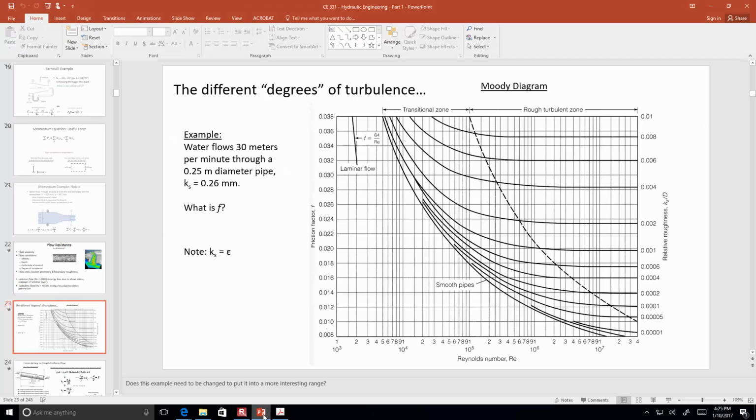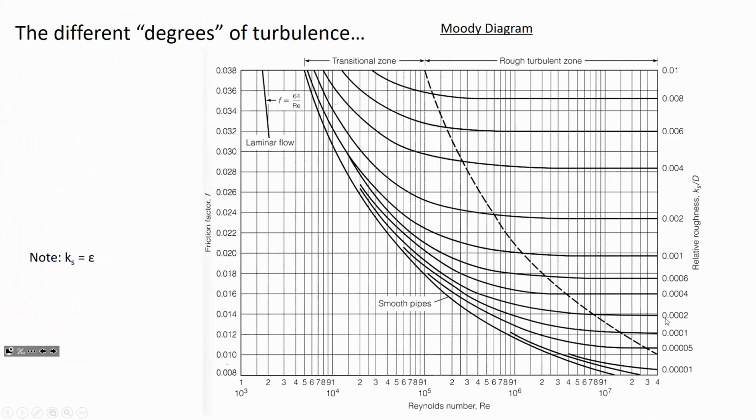So what that means is, over here on this curve, here's the 0.001 curve. We're going to be slightly above that because it was 0.00104. So we need to be just a tiny amount higher. So we're going to follow this curve until we intercept the Reynolds number that we've got. And back from that calculation, it was 1.25 times 10 to the 5th was the Reynolds number.